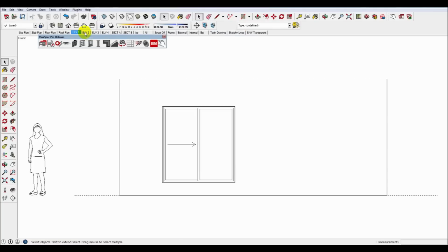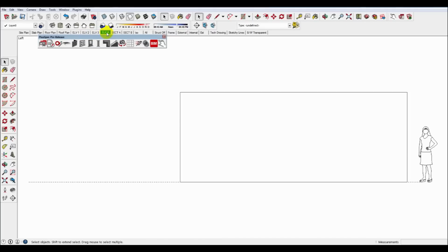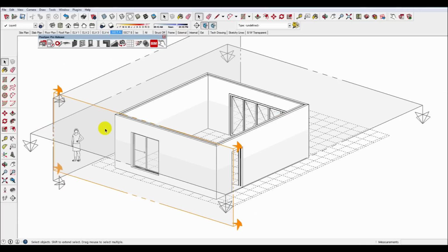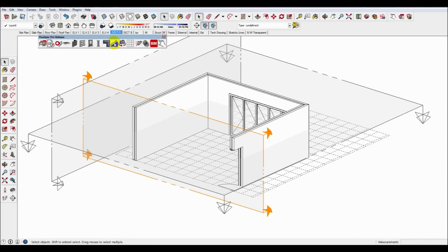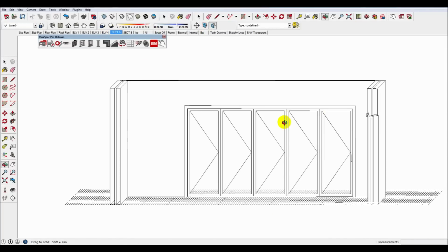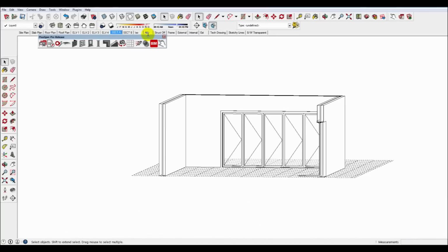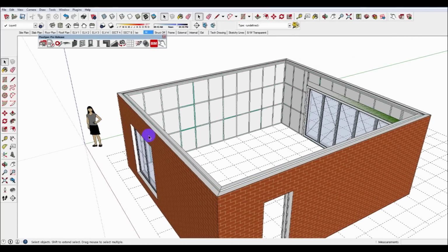I've clicked on it and I've got my elevations. You can change the names of these elevations. You can put scenes in. You can put sections in. There we go. So you notice we've got a section there. Okay, if I turn my section plane off and go back to my section, now I have a section through the house.